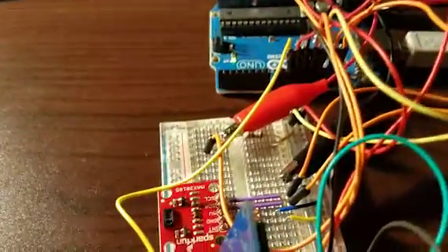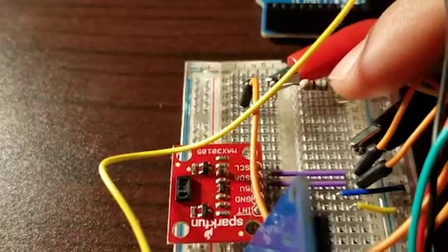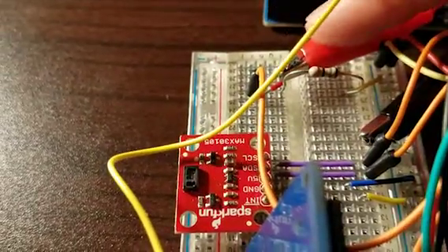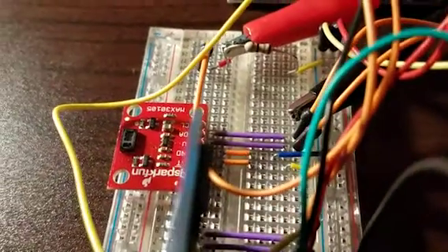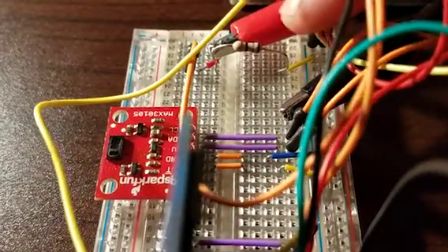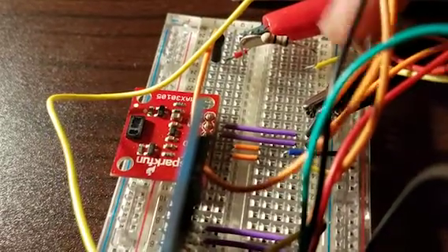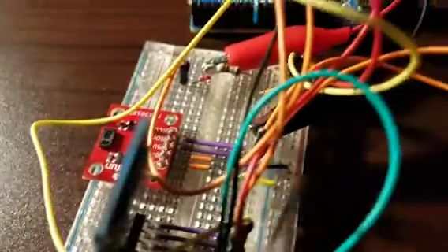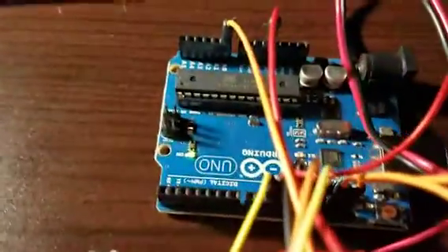And the voltage from the solar panel crosses this resistor, and then here's the high end, here's the ground. And so with that resistor that I found to be maximizing the power, we have pretty good voltage right there that I can measure over time. And then finally, we have the SD card all hooked up to the Arduino, all the pins working correctly.